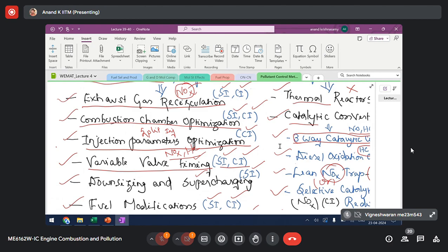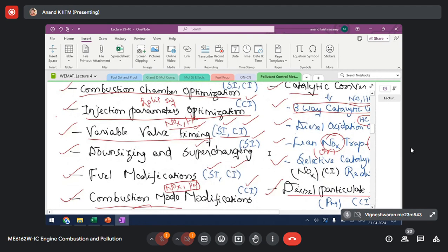So if we do compression also, this backflow will happen, correct, sir? If we keep some turbocharger, anything? Turbocharger will help because you have a boost pressure. The benefit is that the incoming charge has more mass, and more mass means again more inertia. Correct. There are two things that will decide. One is the suction effect in the cylinder, which is going to fix the velocity. The other is the boost pressure. With boost, you have more mass. Correct. Okay, so I will just stop here.